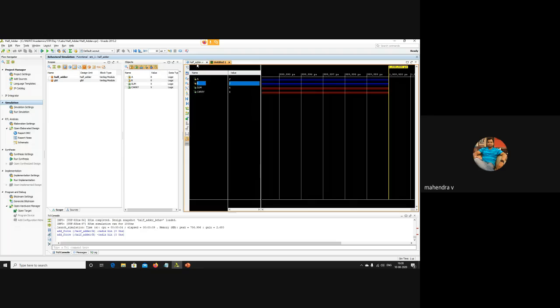After giving 0 0 as the input, now here you can see the simulation time for which you want it to simulate, 10 microseconds or 10 nanoseconds. Here you could see picoseconds, nanoseconds, microseconds. Okay, you can select how much time you want to run it. You can select nanoseconds also, not a problem. Otherwise ideally you can select microseconds. That is the default. You can let it be default.